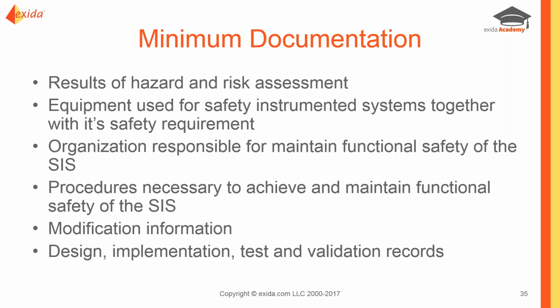Documentation on who's responsible for doing those maintenance activities and the evidence that that work was done. So when we go out and do our proof test, we're looking for the history that the proof tests were done on an appropriate period, that the people were trained and qualified to do what they were asked to do on the proof tests, that we've recorded the as found, as left condition, that we've documented and recorded what information we've come out of the proof test in terms of what's failed, what's not, so we can look at the overall reliability. It needs to be kind of a living type document.